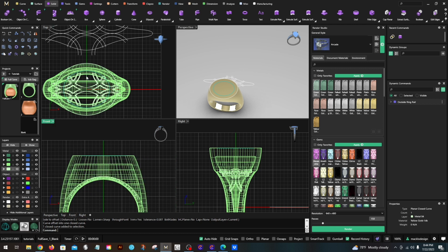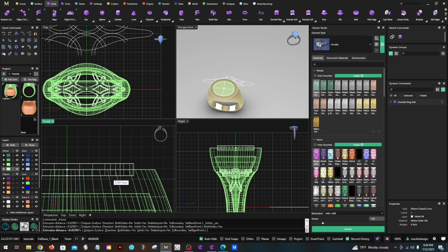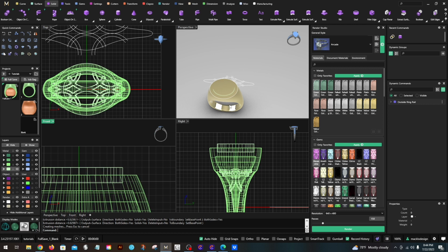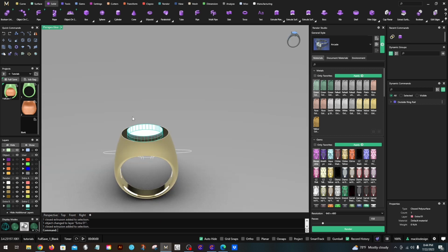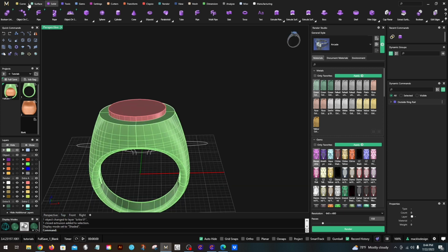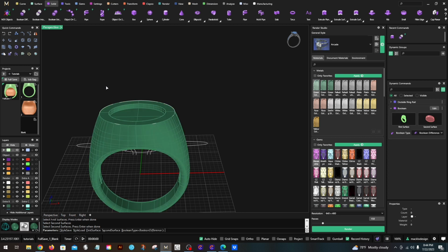All right, now I'm going to go ahead and make a solid, extrude planar curve. I want to do both sides on this one. So I am going to come down about that far because I want to leave enough between there so that casting will go well. All right, and now I'm going to use this as a cutter. So let's go ahead, go to solid menu, Boolean difference, select this as our first, and then this is our second. There we go.